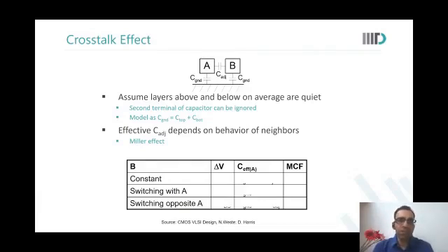So what we usually do is we simply add some parasitic capacitance on every intermediate node. We say, okay, this node is going from one inverter to another, so at least two femtofarad capacitance will come. So we just put some value there, so that our final delays are not far away from our initial targets. Based upon experience? Yeah, based on experience and technology characterization and stuff like that.